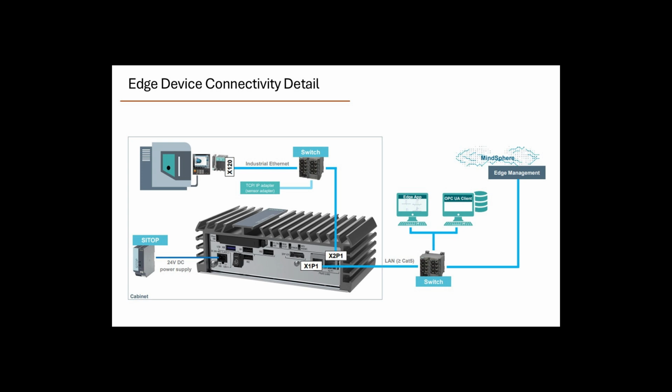One of the points that I want to make in this slide is the ease of connectivity. There's no wiring. It's really just an Ethernet cable from the X120 port on the Sinumerik ONE to the X2 port on the Edge device. It's a device that you purchase, and it literally takes minutes to install on the machine. I'll go back to this one slide here.